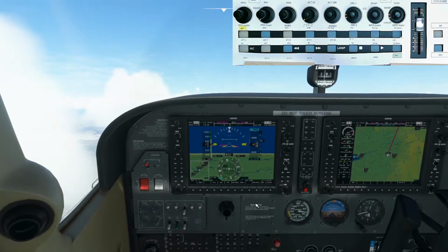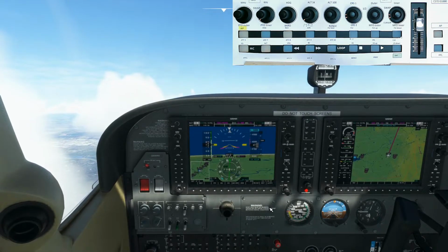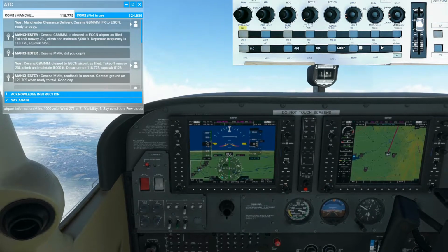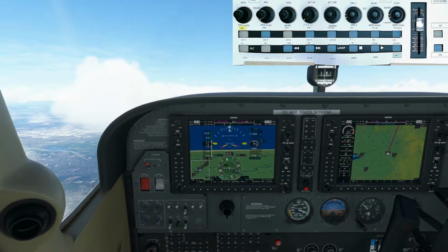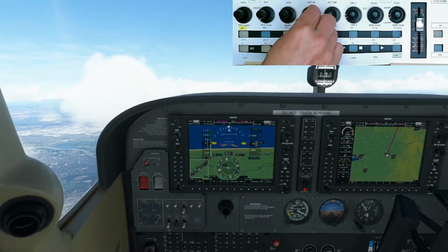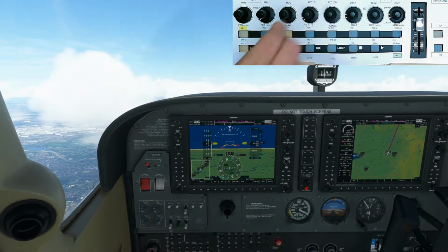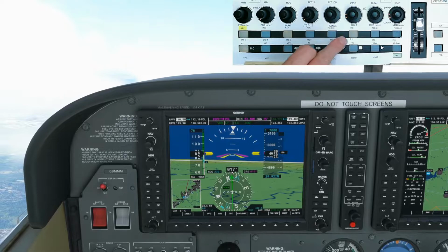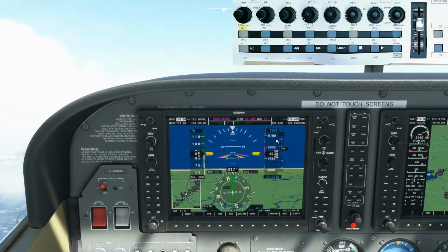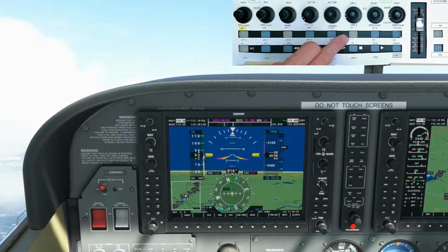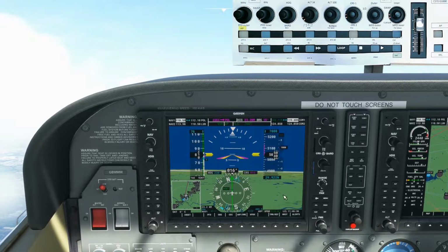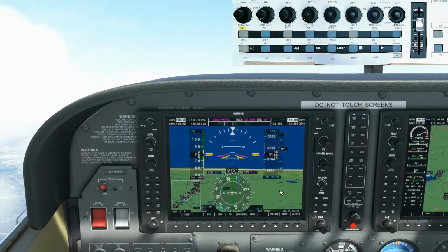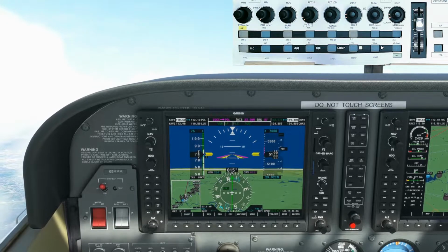We should start leveling out in a moment. Okay, so we've adjusted that for 7,000 feet, but I'll have to pick the flight level control again. We were too close to the 5,000 mark, so it had switched off the flight level change and taken us into altitude hold mode. So we'll honour that, and away we go. So the speed's coming back. As we level out, the speed will increase, of course, so I'll have to come back on the throttle and then check the mixture again.